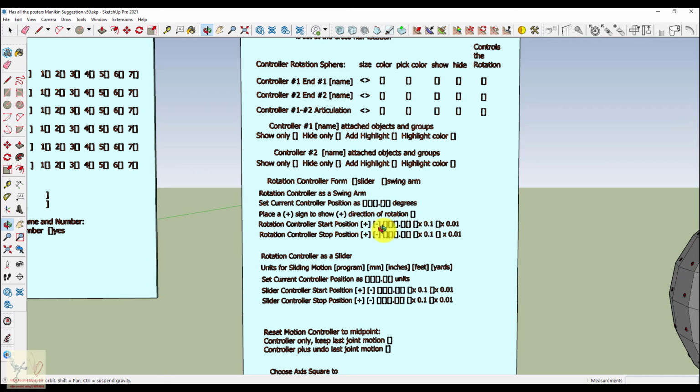So that gives you the ability to specify what it is that this portion of the model can do. And if you ask the model to do something where it has moved more than the range of this specification, then a little sign will pop up and say, articulation tool prevents this motion. That's all.